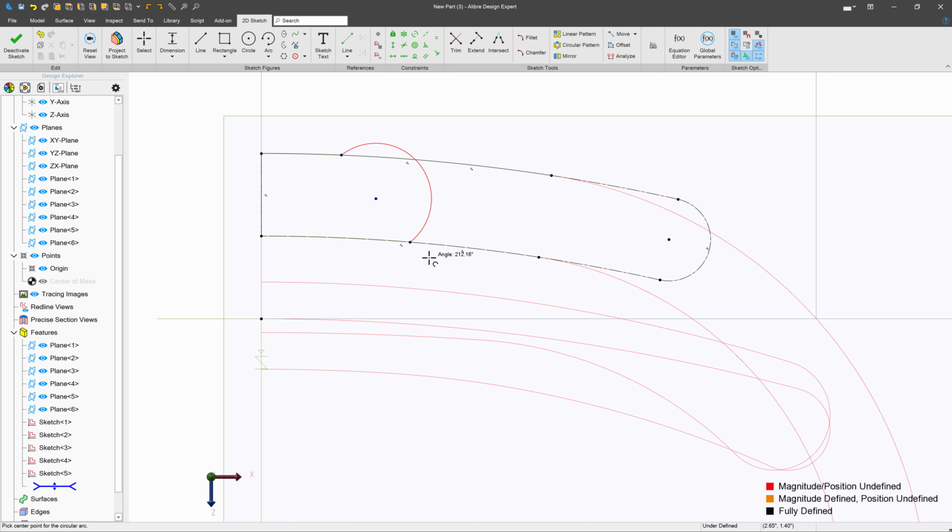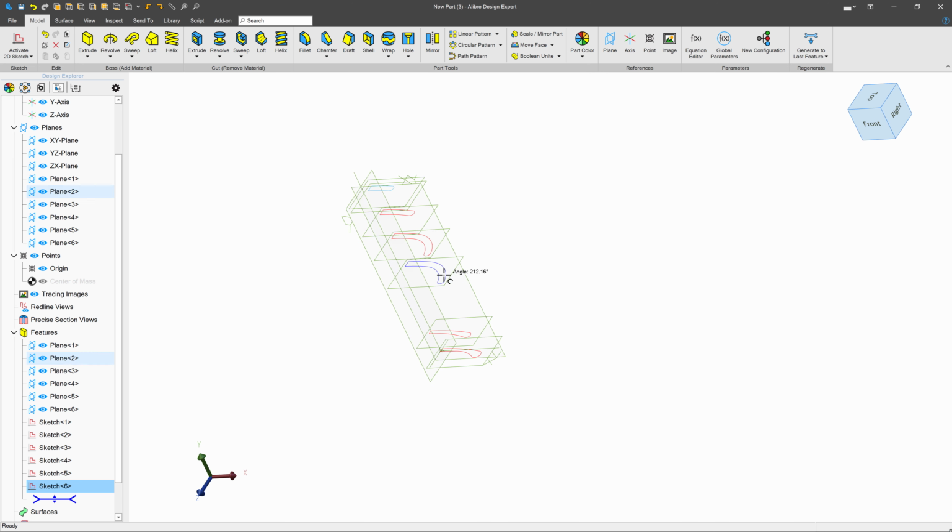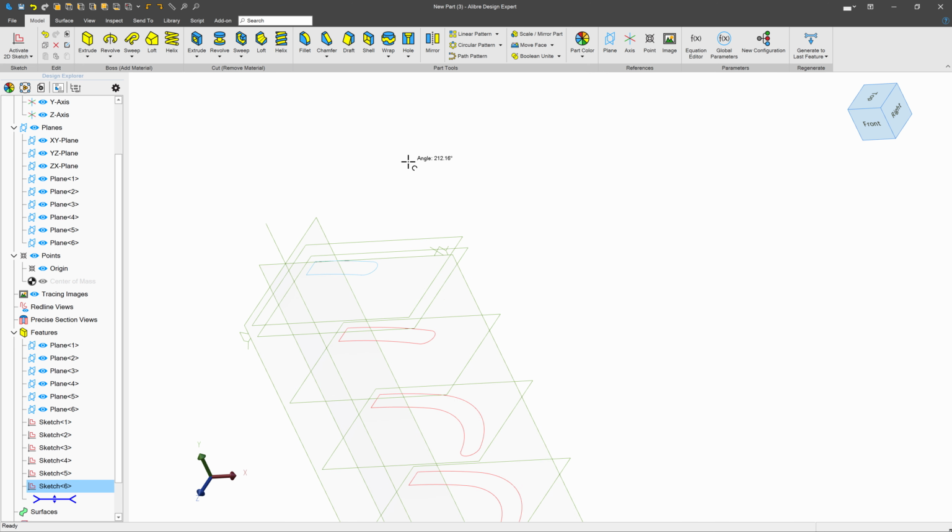An arc from here to there. Very good. Tangent. And tangent. And our only degree of freedom is this one. And we just did one that was 7.35, so let's continue to narrow the top of the chair and make this something like 5. We'll deactivate the sketch, right? So you can start to see the outline of a bucket seat that we've created.